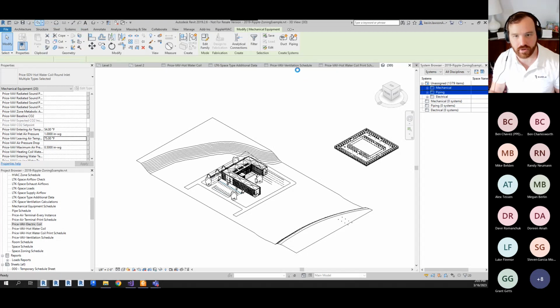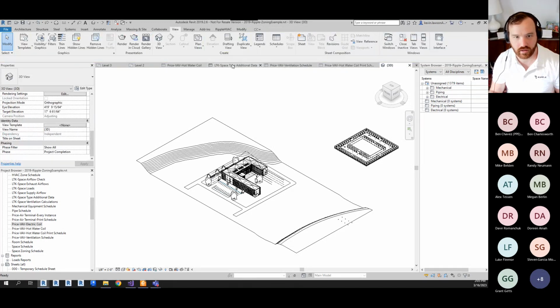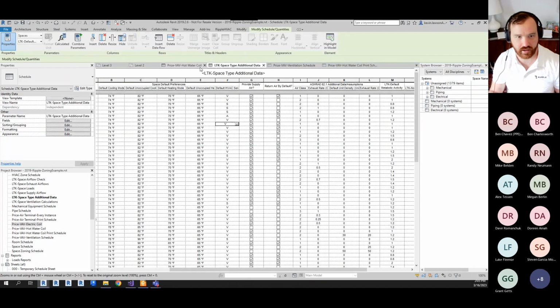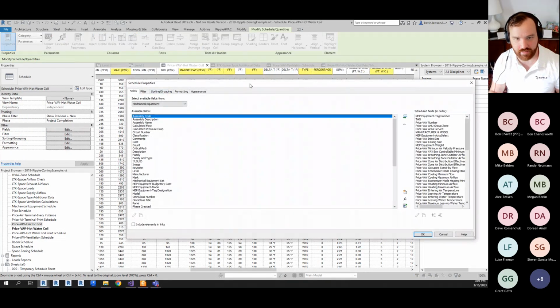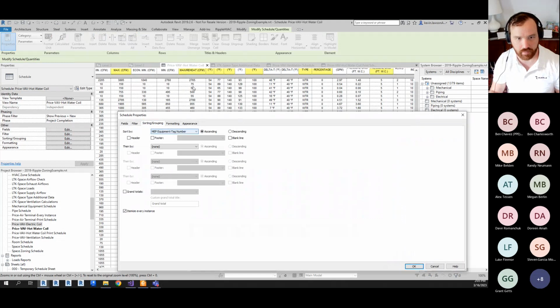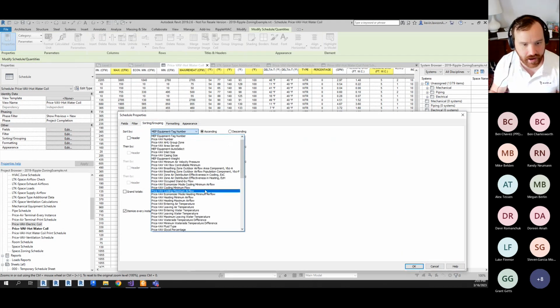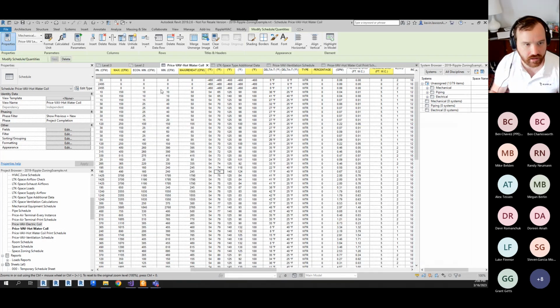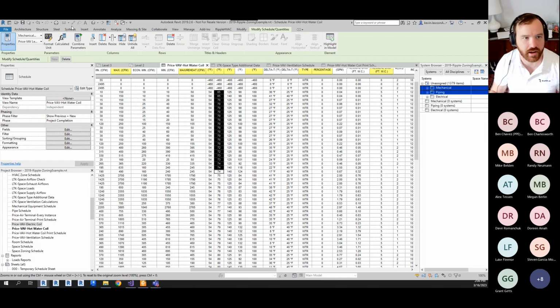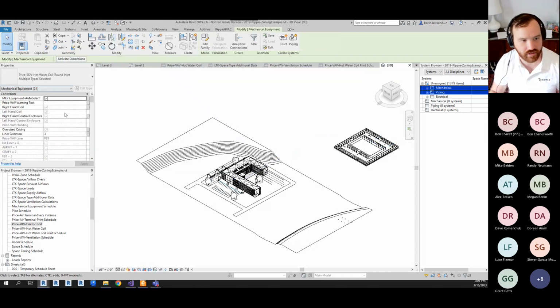What I'm going to do here is, if I wanted to say, here's my hot water coil, and minimum discharge air temperature is 75, I could sort this by my leaving air temperature. The 24 by 16s are messing up for some reason, but I could select everything below this, go to my 3D view, and now I've got these all selected.